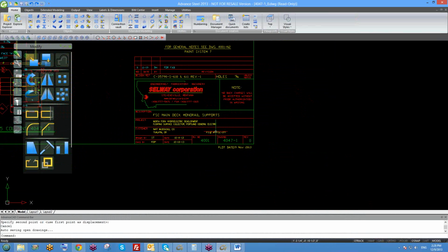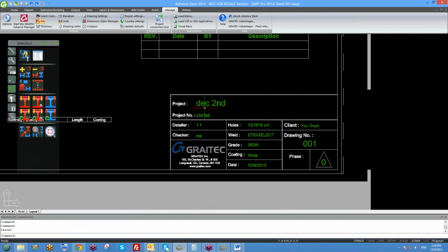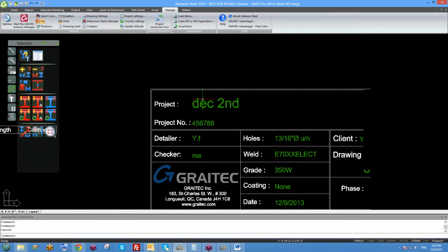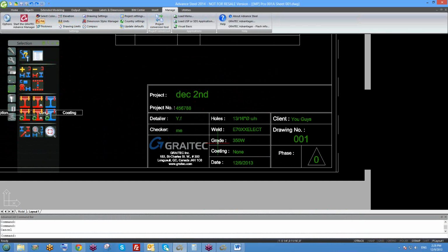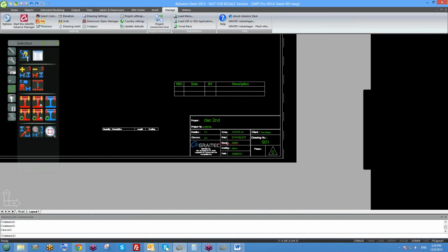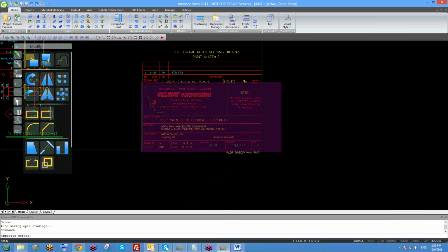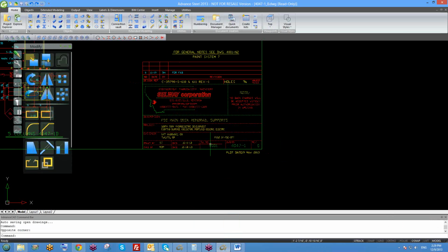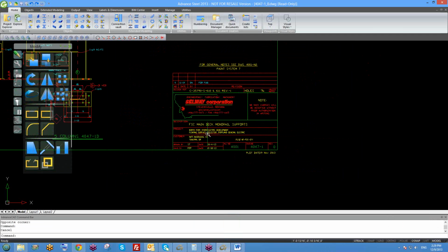If you have some existing title blocks created with a DWG file, you can use the geometry that you created before and just replace these tokens. But if you don't have something like that, you need to recreate the geometry itself. What I mean by that is, in your case, Dave and Jason, you don't have to create the whole geometry. You can use the geometry you created before and just replace those tokens with these simple text in your title block. I'm going to show you how to do that, but you have two options.